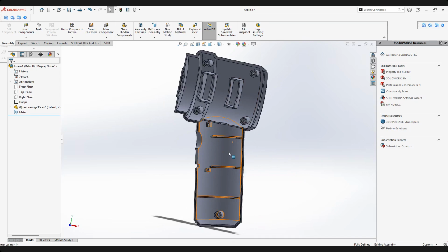You are holding this on your palm, this is your rear casing. Then do I put the battery first, or motor first, or PCB first, or rear cap first? Because if I put the rear cap first, then later when I want to mount the motor, it is blocking. So the rear cap cannot be number two. Be careful about it.